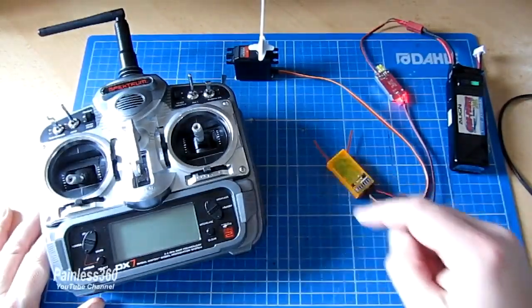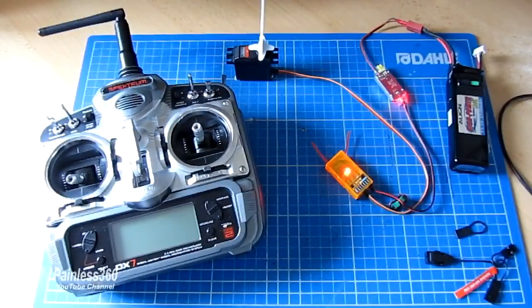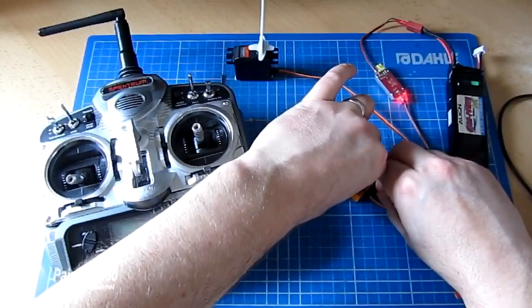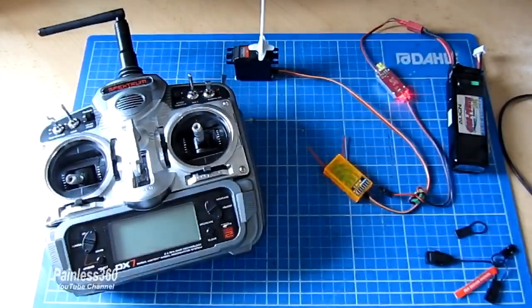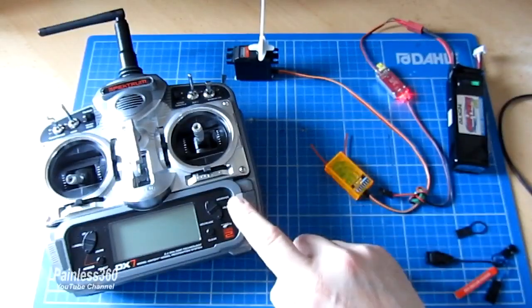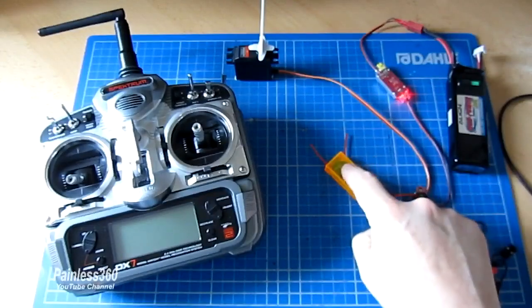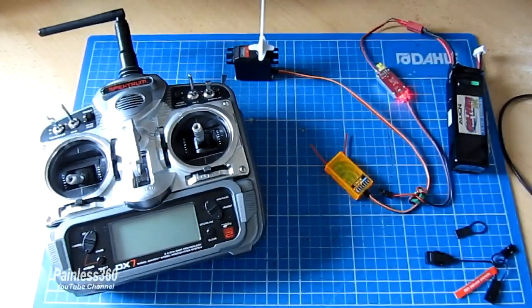So we have to bind each of the receivers to the radio and the specific model memory that we're interested in. Now, the next thing we'll do is let's actually rebind this, because not only do receivers store the connection and the security handshake between this receiver, the radio and the model memory, but a number of receivers also have failsafe.